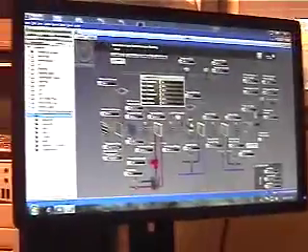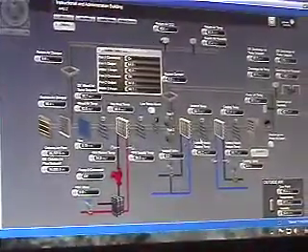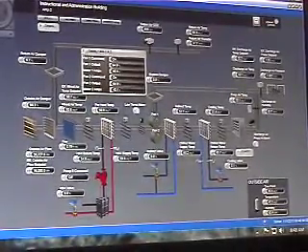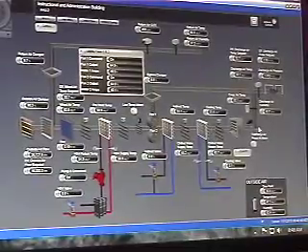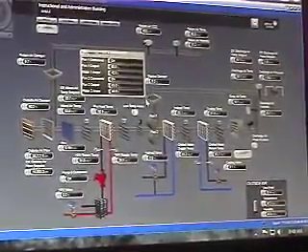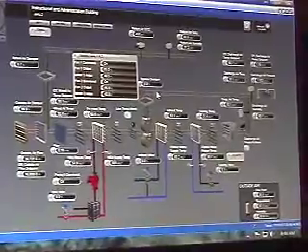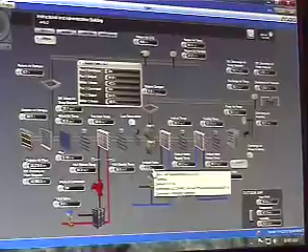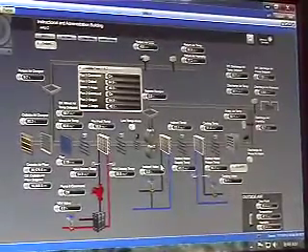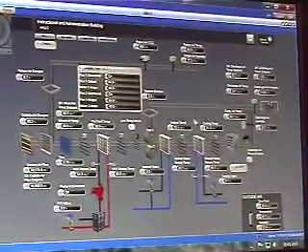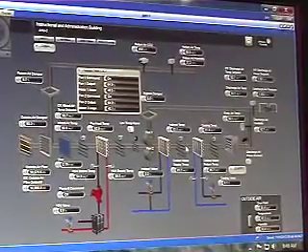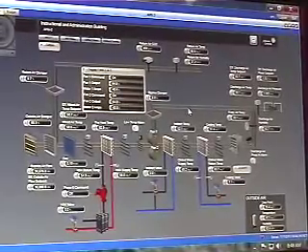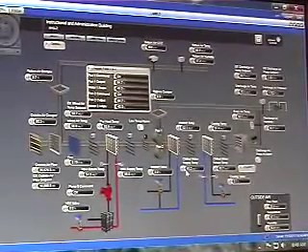Here you have your 2 fans. From here you have the ability, I'll explain this in a little bit more detail, to either bypass the coil sections and go up and around out to the building, or to feed through the coil section. The only time that this damper is in action is when we're running the evaporative media mode. Here, indirect valve coming from your cooling tower. These temperature sensors here, indirect and cooling temperature, are there for monitoring purposes, not so much controllability. It just gives you the ability to look at what your temperature drop across the coils is.